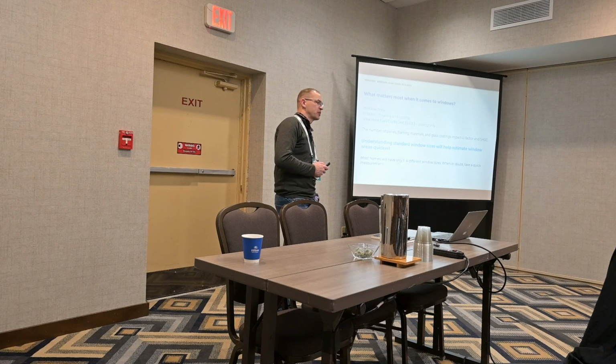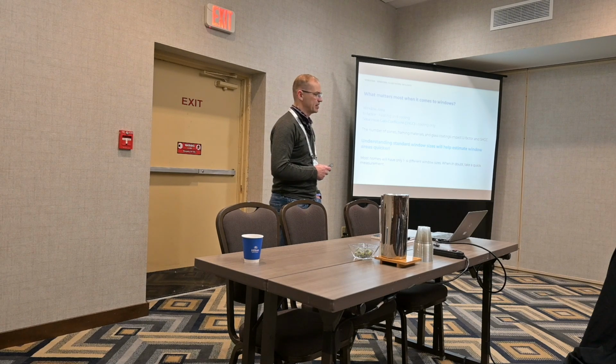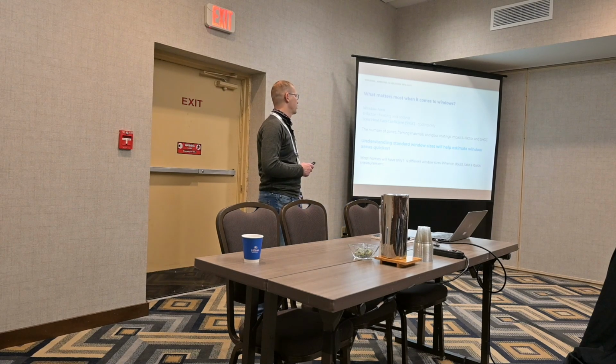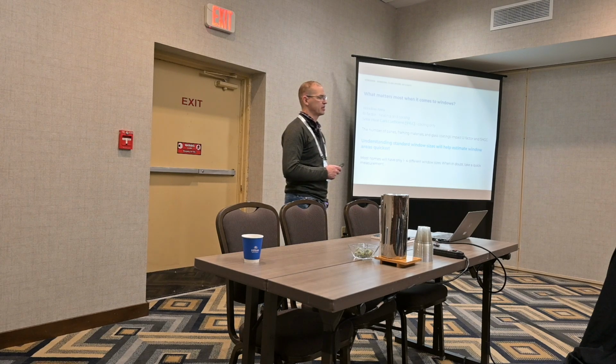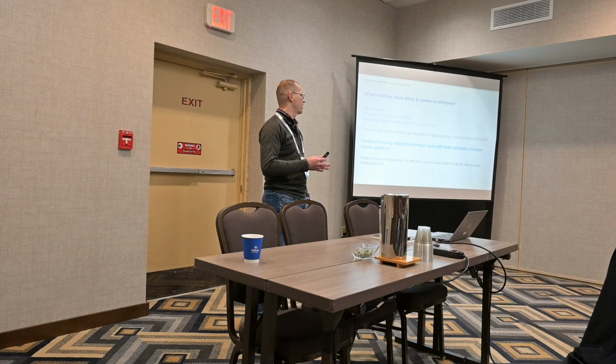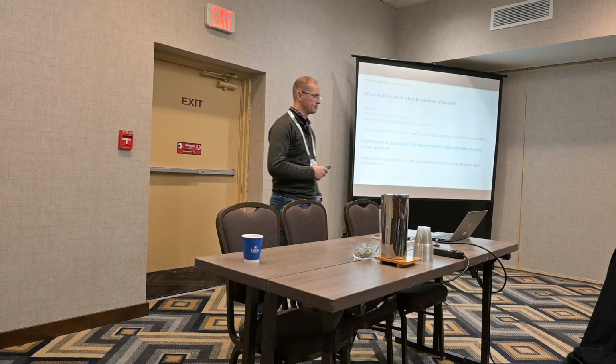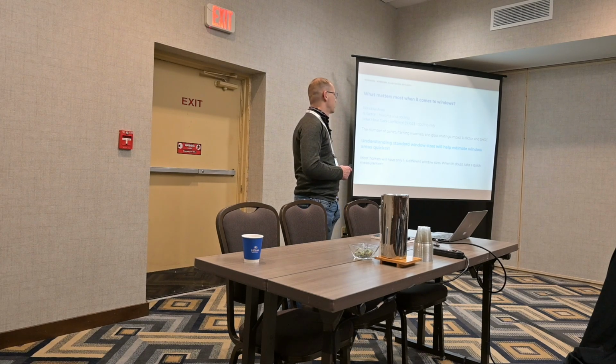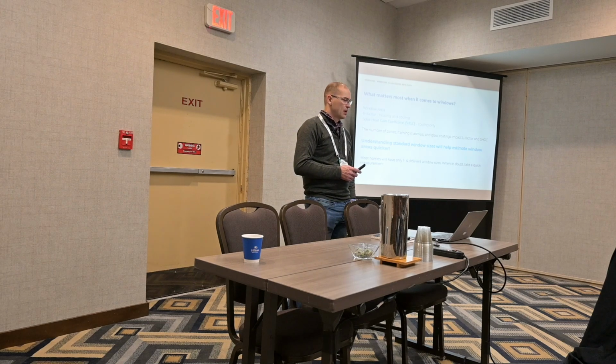Okay. So what matters most when it comes to windows? Window area is one of the biggest things that impacts heating and cooling. The U-factor comes second, and then your solar heat gain coefficient is for cooling only, not heating. Still, it should be done even in states like New York where we're cold climate. And this will help determine how the heat pump will operate during the cooling season. Number of panes, framing materials, and glass coatings impact the U-factor as well as the solar heat gain coefficient.